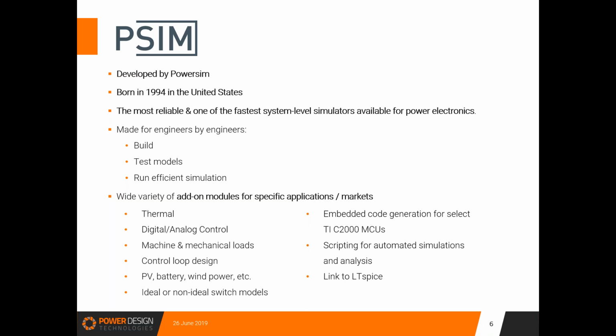And then also we're pushing to LTspice now. So PSIM allows you to dual define switch models and link to LTspice. Although I would strongly discourage trying to run a Spice simulation of a multi-level inverter topology. That is definitely what Spice cannot handle. So with that, I think I'll pass back to Guillaume.